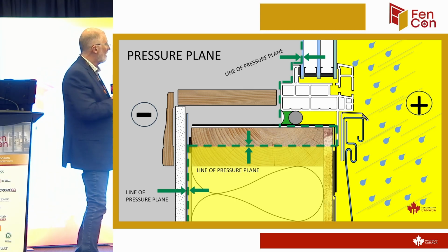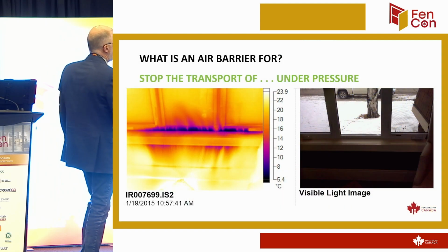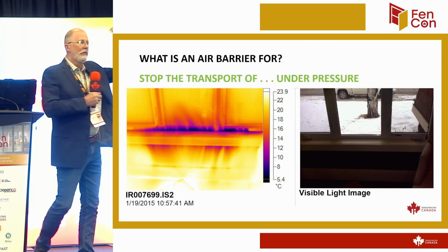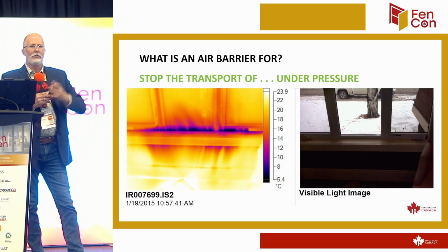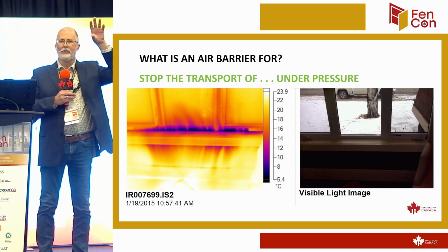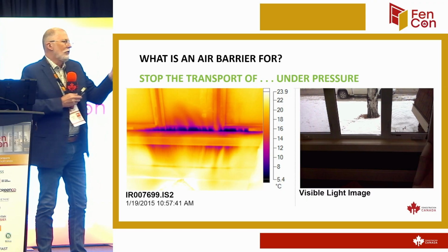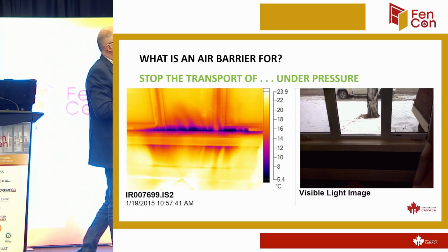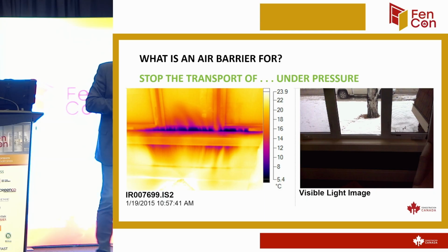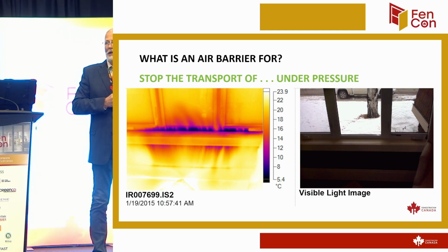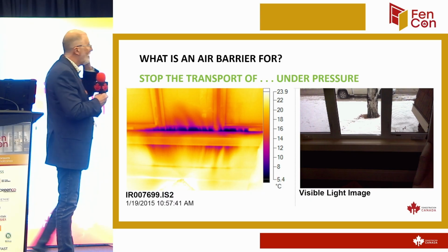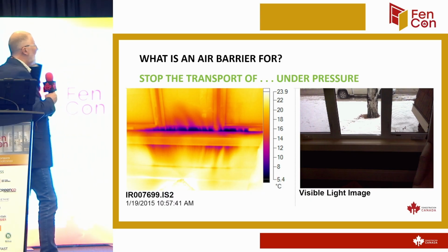And that's the principle of curtain wall systems. When you look at high, tall buildings, when you think of a curtain wall, it treats the glass or the glazing as porous. The water gets in and around it and it just drains back out. Like, how could you resist 400, 700, 1,500 pascals of pressure on a tall building unless you did that? You can't seal it up perfectly enough. So it's oftentimes very difficult to seal it.